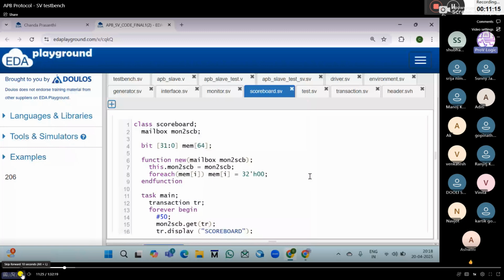Same for the I2C protocol, we generated the finite state machine with a different number of states, designed it and also verified it using SystemVerilog. In the same way, for the APB protocol there is a small FSM with 3 states. By using that FSM, we can generate the FSM code.